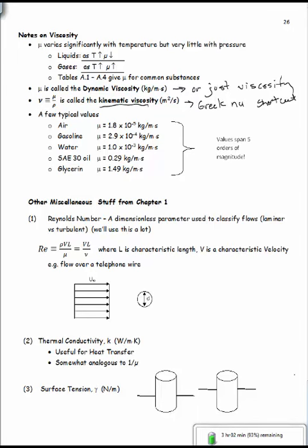One of those is a Reynolds number, and Reynolds number does involve viscosity for sure. So Reynolds number tells you whether it's laminar or turbulent, or how turbulent something is. So when it's laminar, it is dominated by viscosity. And if it's turbulent, it's dominated by inertia. Okay, so the Reynolds number gives you an idea, which is it, laminar, turbulent, or how turbulent.